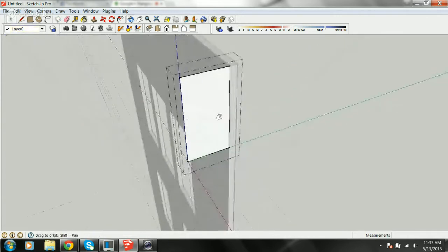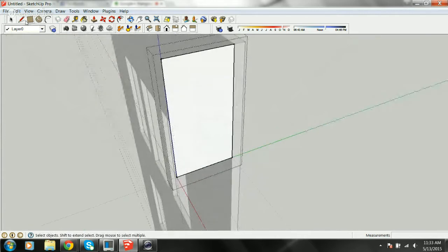So let's get in. Now I'm within the group. I'm going to start at the bottom, and you'll see in my little section, I've only indicated a couple of dimensions. So I'm just going to talk and draw through this. We may change some stuff. It may be perfect when I'm done here. I haven't done this part yet to test it out, so we'll just see how it goes. I've got 8, 12, 8, and 8, which adds up to 36 inches. I haven't given any dimensions to these pushes and pulls, but let's come out an inch. Keep in mind, I'm on the green, red, and blue, so it should always be green and blue in this particular case, based on the plane I'm in.